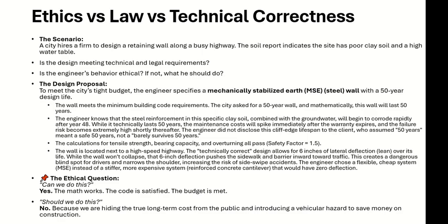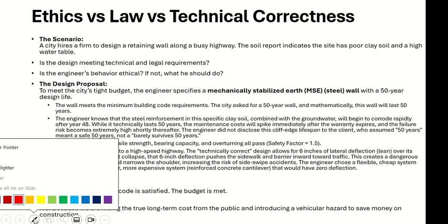So if you go, you will see that the bridge has a slope under it. Okay, so if you don't give the slope, if you make it straight, then under the load, whatever you are having under the bridge may fall. Okay, so in this case we have the slope, but if you cannot build the slope, then you have to build a retaining wall. Okay, so retaining wall is like, let me